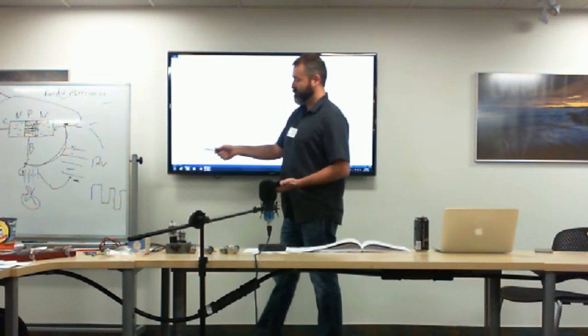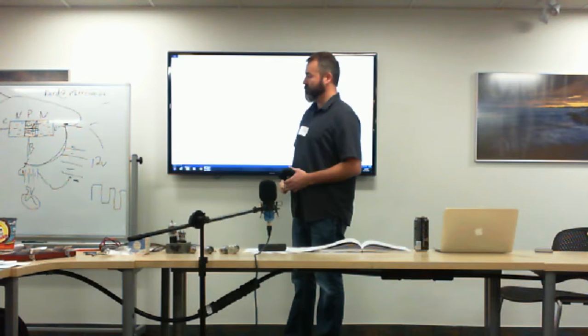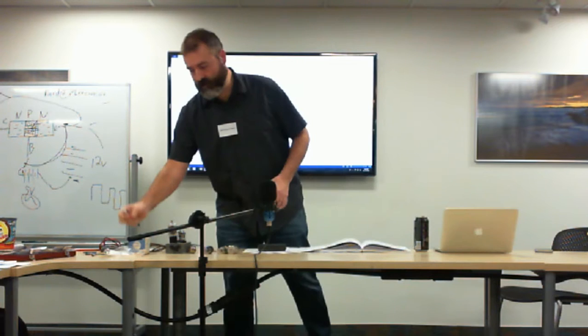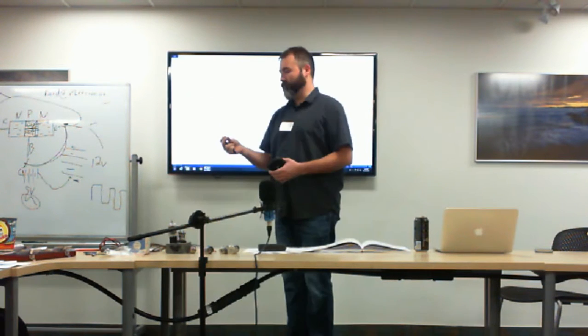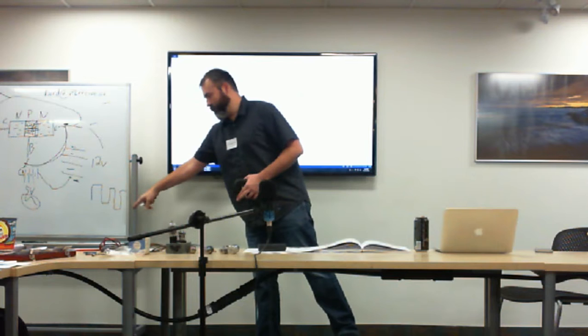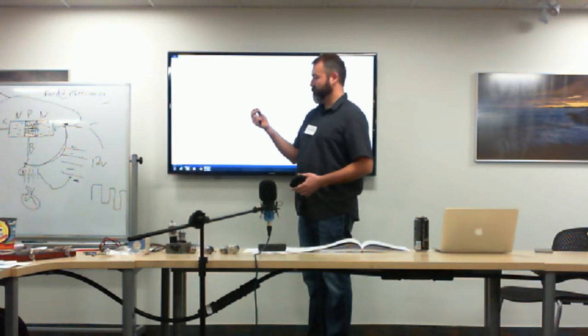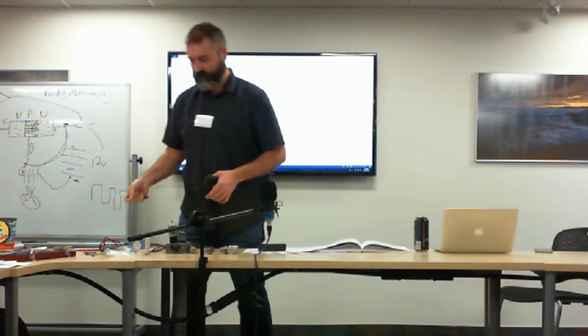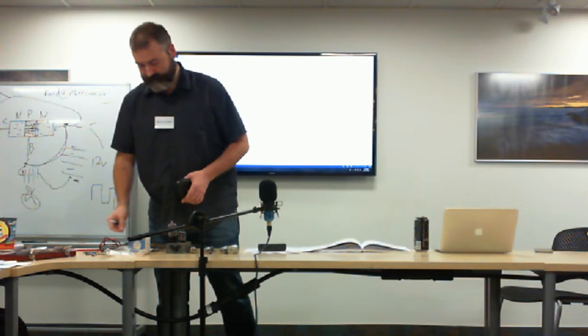So it's using it as a switch, a very fast switch, but we can use it to modulate the speed of real world devices. They do the same to modulate the brightness of a diode, using pulse width modulation. They frequently turn on and off the transistor, which controls the LED, because LEDs last a lot longer if you use PWM. Let's say for 50% duty cycle, they're still quite bright, and you'll double their life, because they do have a life expectancy. It's almost like a dimmer.